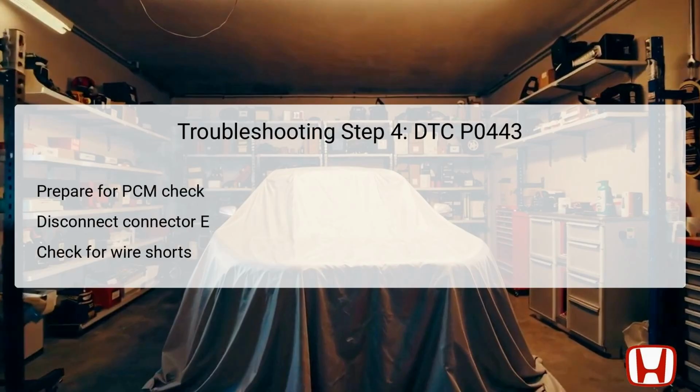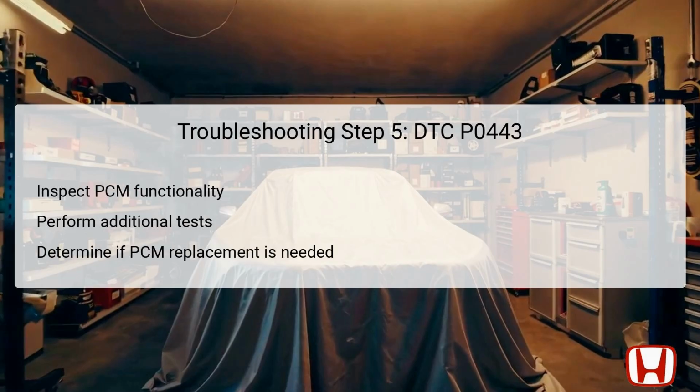the EVAP system. The final troubleshooting step involves a thorough inspection of the PCM, especially if previous tests have shown normal conditions with all other components. If the PCM is determined to be the sole remaining suspect, additional diagnostic tests should be conducted to verify its functionality. This may include examining the software versions, checking for corroded terminals, or any signs of damage on the module